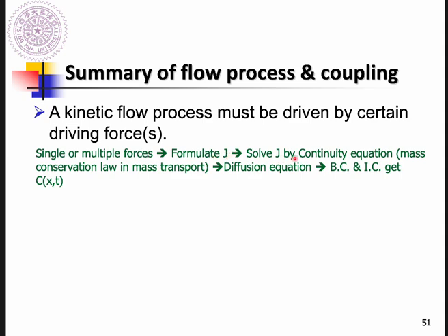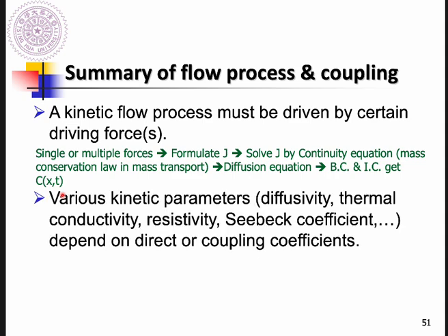Then you can also solve for the flux by continuity equations, which can be the mass conservation law in mass transport. Then use this to get the diffusion equation and solve it with boundary and initial conditions. And finally, I hope you can get how the concentration of diffusing atoms changes with location and time.